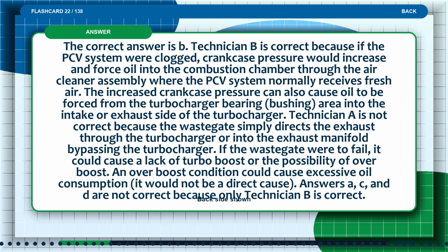Technician A is not correct because the wastegate simply directs the exhaust through the turbocharger or into the exhaust manifold, bypassing the turbocharger. If the wastegate were to fail, it could cause a lack of turbo boost or the possibility of overboost. An overboost condition could cause excessive oil consumption, but it would not be a direct cause. Answers A, C, and D are not correct because only technician B is correct.